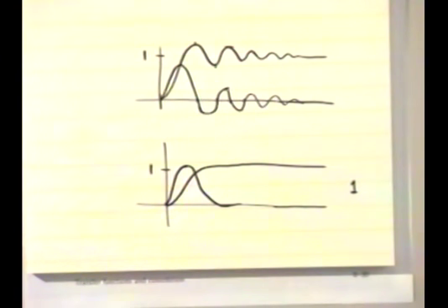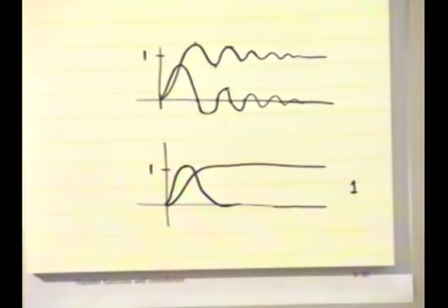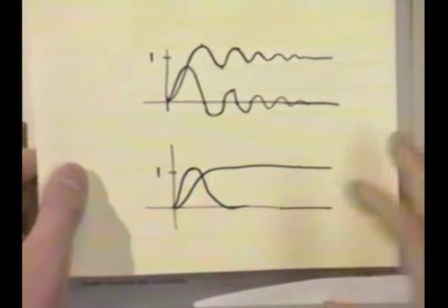Okay? So, and again, we get this all just from impulse and step response and stuff like that. And I guess that makes perfect sense, right? If you have an underdamped mechanical system, and you walk up to an underdamped mechanical system and then shake it right at about the resonant frequency, of course it's going to be amplified by a lot. And so all of this we just got directly from looking at this, okay? But we could for example, I don't know, on a homework problem or something, I don't think we have, but on the homework problem we could certainly ask for actual numbers here and ask you to reconstruct the worst possible types of speed bumps and all that kind of stuff. But you get it all from here. Okay.